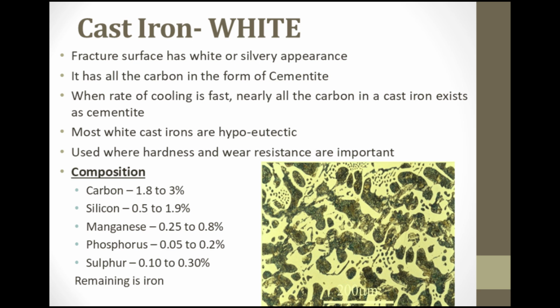Composition: carbon 1.8 to 3%, silicon 0.5 to 1.9%, manganese 0.25 to 0.8%, phosphorus 0.05 to 0.2%, sulfur 0.10 to 0.30%, remaining is iron.